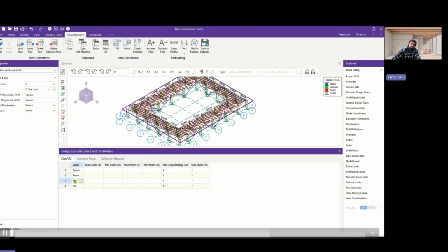like how much the minimum depth or the maximum depth, and the utilization ratio you want to set. So for beams, columns, girders, and the braces, I am going to create member design rules. For example, for girders I want to write a minimum depth of 14. For example, if you are using the AISC manuals, the 14 depth has been written as 13.9. So if you write just 14, the shapes will not be selected. So I've written 13 here to consider that shape as well.